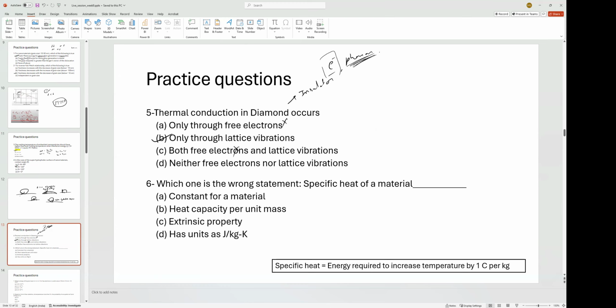In some PC cooling gels, they have diamond particles inside. Diamond is an insulator, so there's no risk of shorting your chip components, and it has very high thermal conductivity. It gives your gel good heat transfer capability.